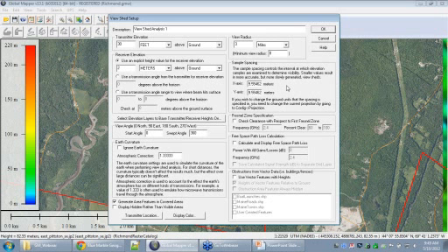This is a really big one. For folks that are doing coverages over large areas, if you're talking about things like radar mapping or cell phone mapping coverage, you don't need to have this at an incredibly granular level. You're going to be able to turn that up. And if you're doing a very large area at a very fine sample spacing of just a couple of meters, it's going to take you a while because it has to do a whole lot of line of sight calculation. If you're doing a smaller radius, obviously you can really turn that down to a much finer resolution.